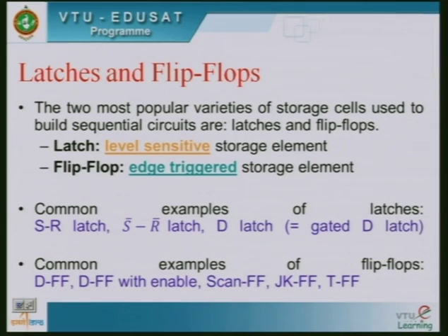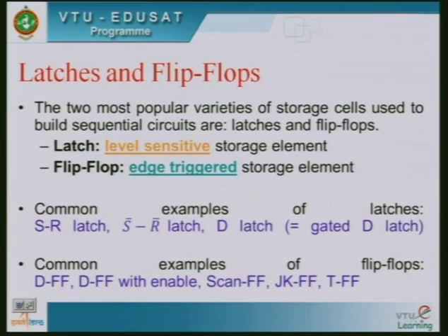In a flip-flop, edge triggering is used, whereas in a latch, level triggering is used. If I give an enable signal, only when the enable signal is high does the circuit behave as designed. If the enable signal is low, the circuit will not work. That is how a latch works, whereas a flip-flop uses a square-like clock signal, and at every edge a change will be detected. So, this is the common difference between a latch and a flip-flop.